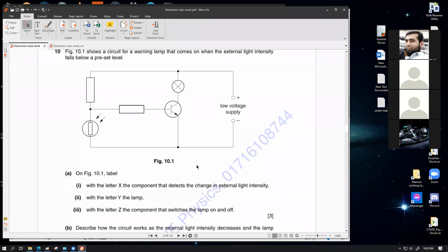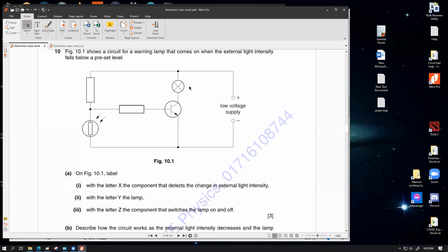A practical use for this circuit is street lamps. You attach this LDR on the top of the street lamps, which takes the signal from the sun. When the sun goes down, the LDR drops into darkness and the street lamp lights up automatically. When the sun comes up, the LDR is in brightness and it switches off the light bulbs.